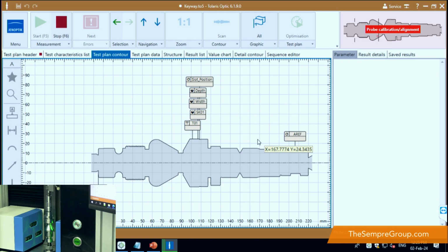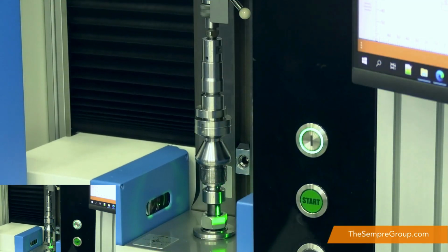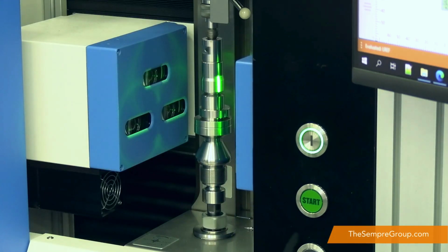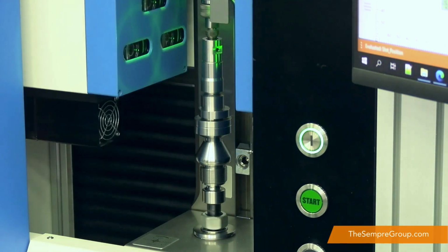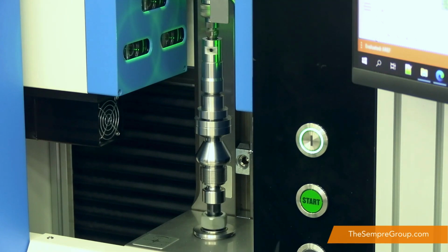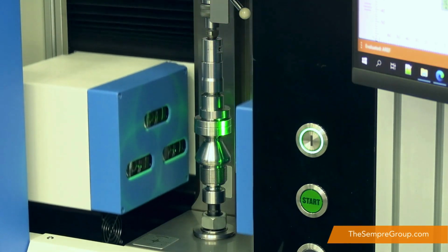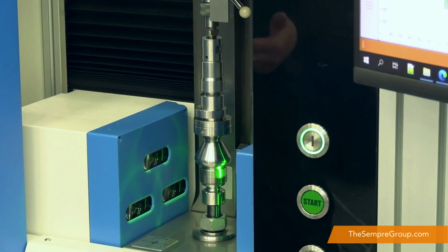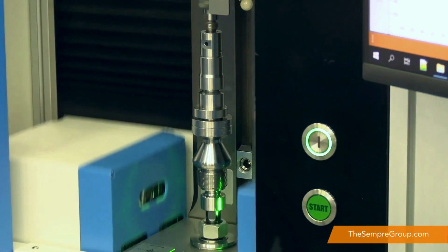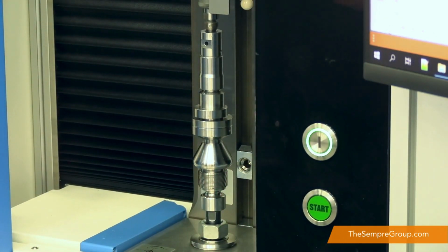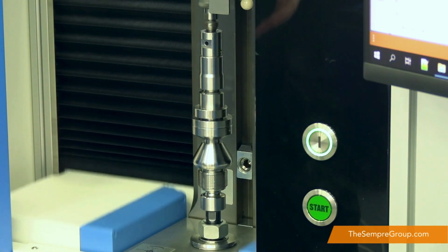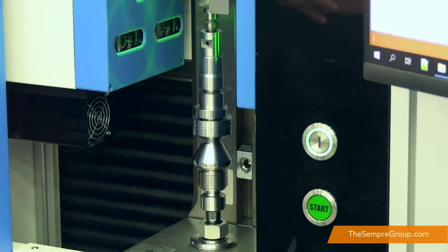So this is quite a key point to note. So the probe is currently running through a calibration. So within our INI file on the system, every 20 minutes we do a reference run to make sure the probe's still intact and it's measuring within an allowable limit. It's quite important. These machines are used for production environments. So if there was to be a drift or someone was to knock the probe, we shouldn't lose any more than 20 minutes worth of measured data. It's something that Genoptic have embedded into the systems. We do the same with the optics.